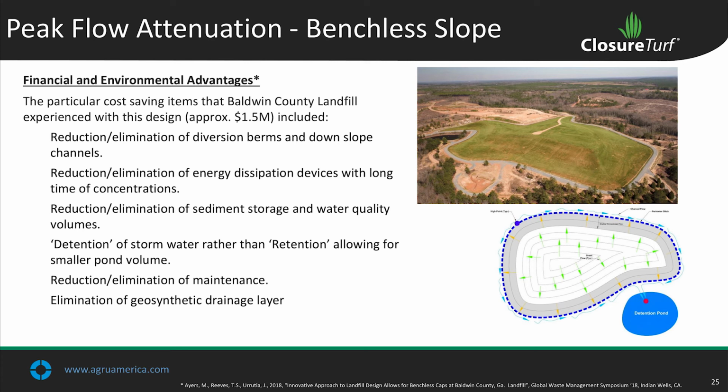Another method is outlet improvements out of this brown detention pond, since it's full of sediment. And this could involve something like a spillway weir and sluice gates to temporarily increase storage during that peak flow period.